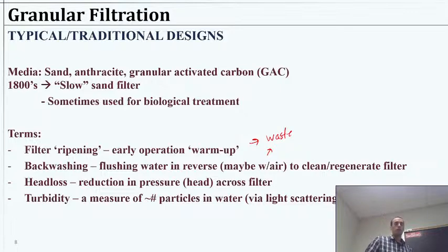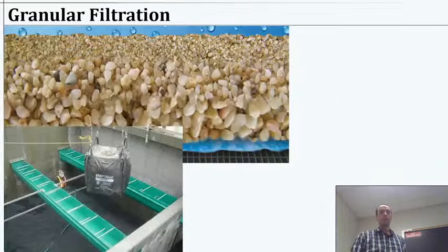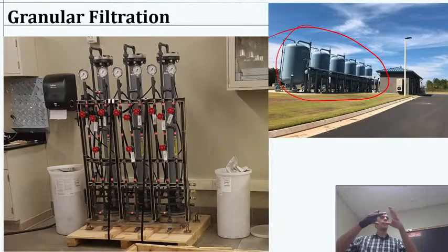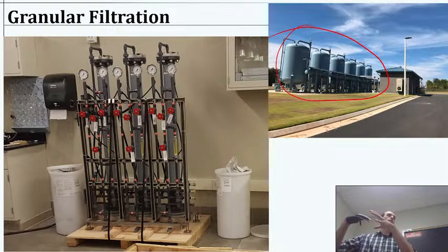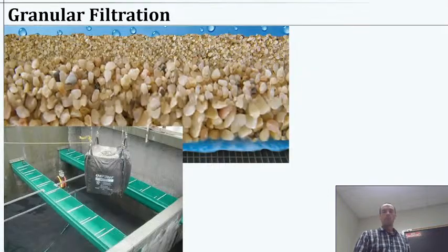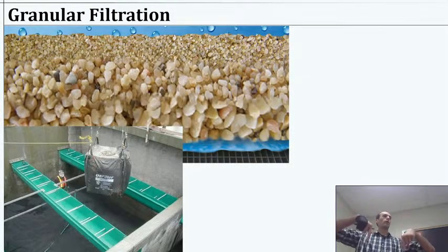Okay, so the other term I want to cover is head loss. We typically load our filters by gravity. That's a little different in the case of the one I just showed. In these containerized or pressurized systems, you would add pressure just by pumping. So it's a watertight system. You pressurize it with some sort of pump, and you're pushing water through that way. Most of the time we operate with an open bed, and it's just gravity that's pushing water through.